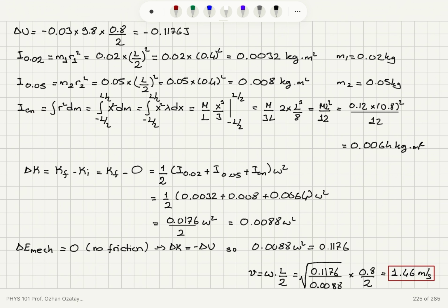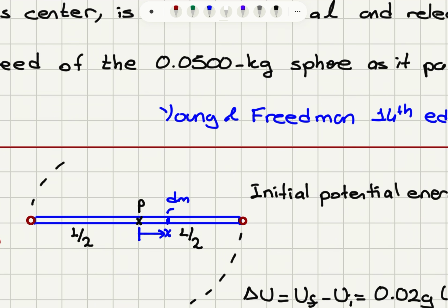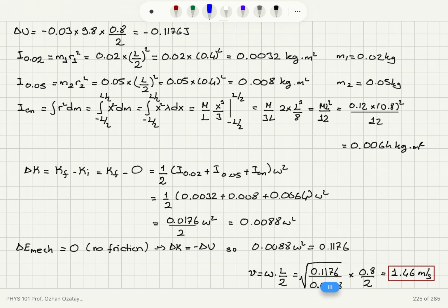And for the moment of inertia with respect to the center of mass of a uniform rod, this is a calculation we have done before in the previous problem as well. This is just the integral of r squared dm, where r is the distance with respect to the rotation axis. So if this is the x-axis and I'm at a distance x, this mass element will have a length dx, and lambda times dx is its mass. So dm is equal to lambda times dx. So r squared dm then becomes lambda dx times x squared, integrated over all possible x values.